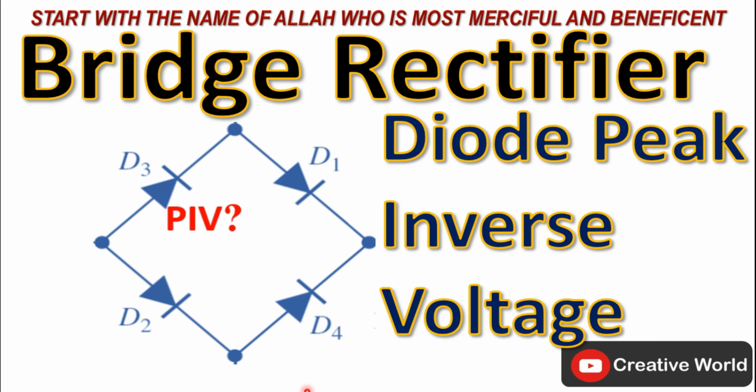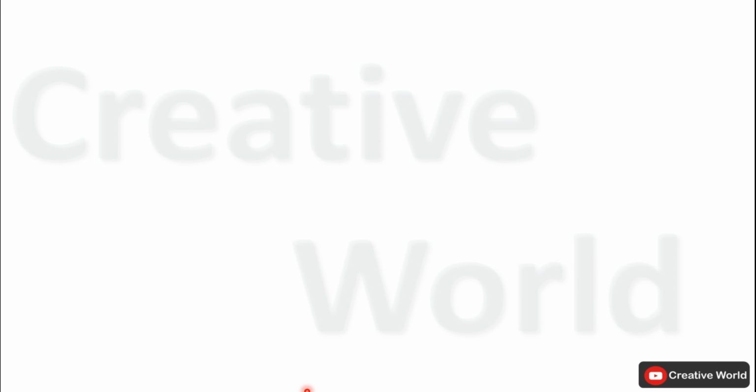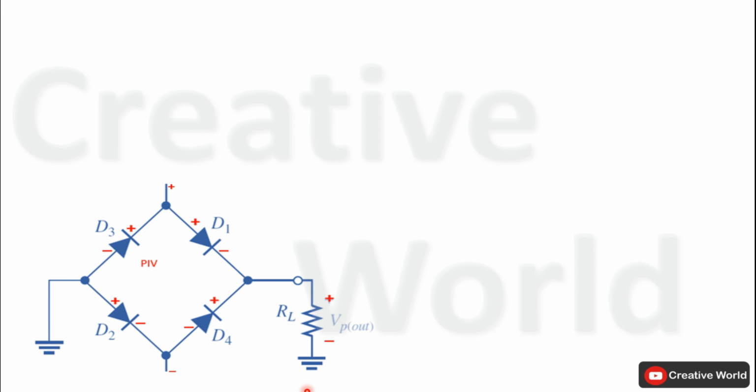Welcome to Creative World. In this video, we will learn how to find peak inverse voltage across reverse biased diodes in full wave rectifier bridge configuration. We know that in case of bridge rectifier configuration, at a time two diodes are in forward biased while remaining two diodes are in reverse biased. We are interested to find the peak inverse voltage equation across reverse biased diodes.